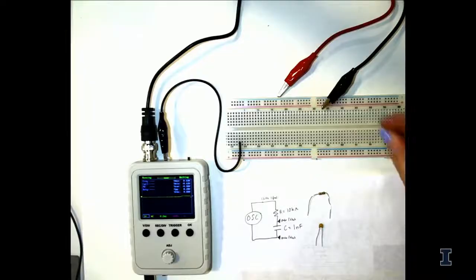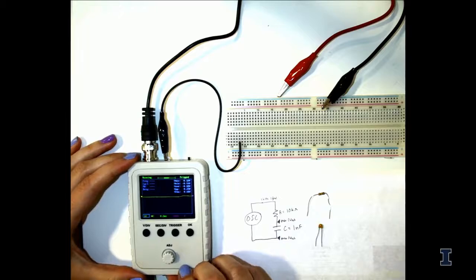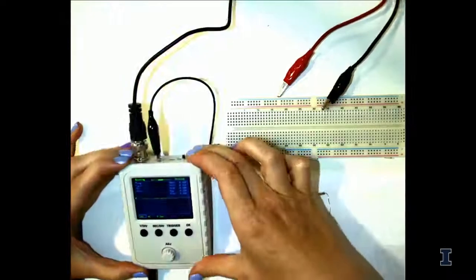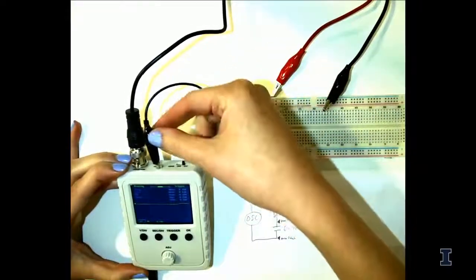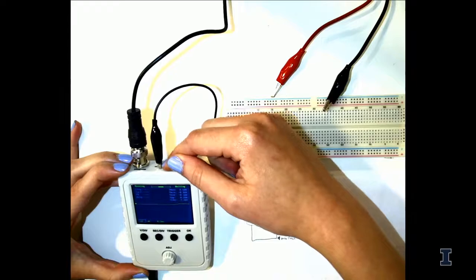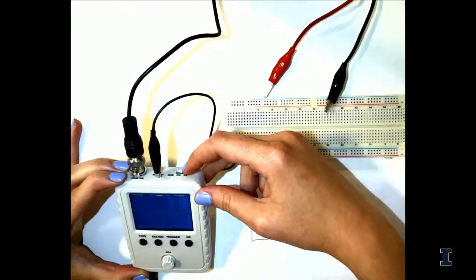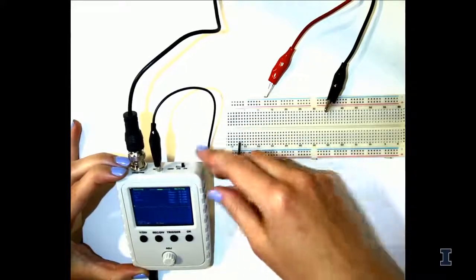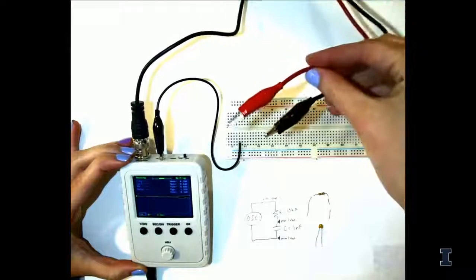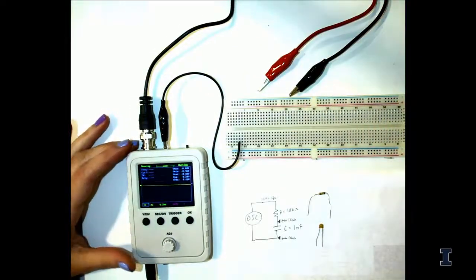So we're going to start by turning on the oscilloscope. You can turn it on at the bottom. It's plugged into power, just the bottom there. At the top, you can see I have an alligator clip on the 1 kilohertz signal. It's the little metal knob sticking out of the top of the oscilloscope. And the switch should be turned on to AC because we'll be measuring an alternating current signal. You also want your alligator clips attached and ready to probe your circuit and measure the capacitor value.